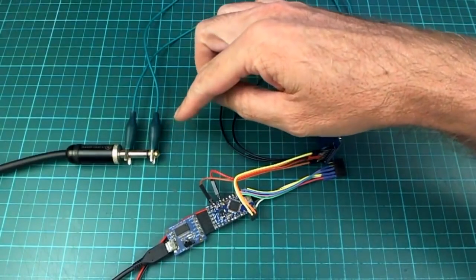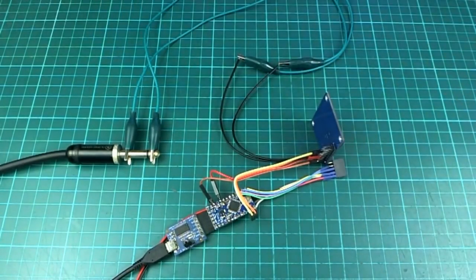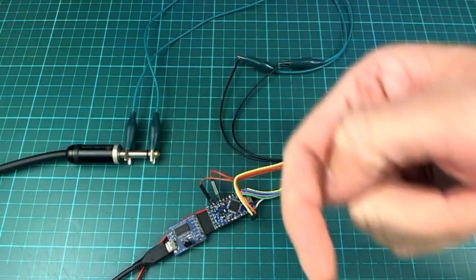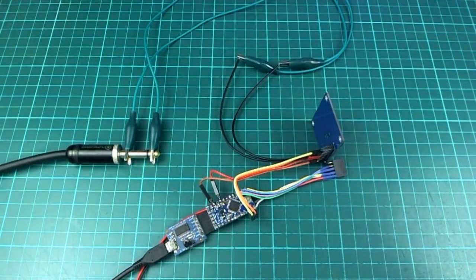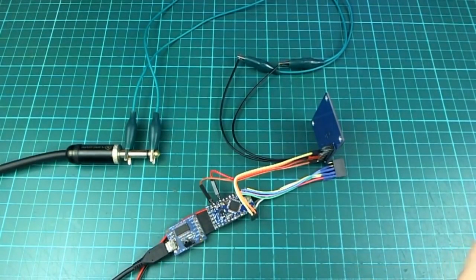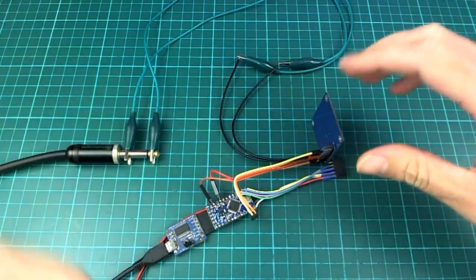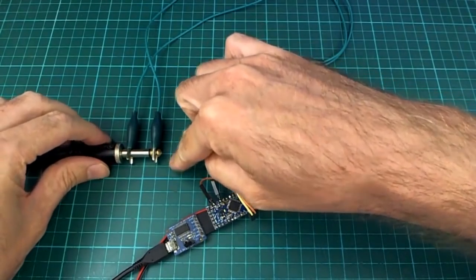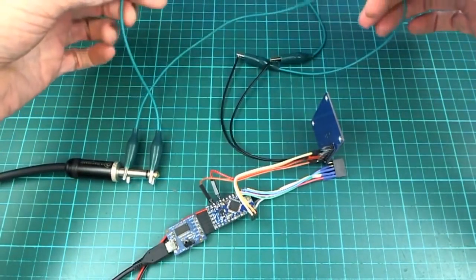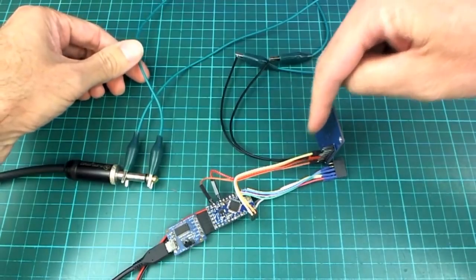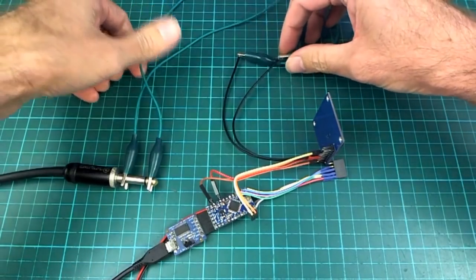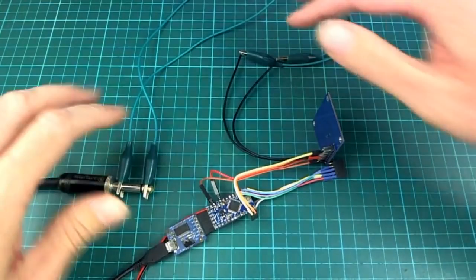And I've got this plugged into a little mixer thing that I use to record my talking when I'm doing these YouTube videos. I could have put this to come out into a loudspeaker and then recorded it into this microphone that I'm using to record my voice, but I figured that people might be curious about exactly what this sounds like, because the quality of audio is something that's probably quite important when you're considering using something like this. So I wanted to record the exact audio that this thing puts out, and it's going to be mixed in with my voice. So you'll see here that there's a little bit of unprotected wiring, so ideally if you wanted nice clean audio it would be shielded, but this is not shielded, and we've got about 40 centimeters of wire that's unshielded. So in theory you might be able to get slightly better audio quality than this, but I think it's still not too bad.